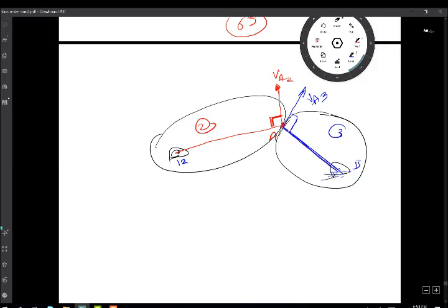And so on each link it's not the same velocity, because the way the contact is made is all based on geometry more than anything. And in this case, that's not rolling contact, right? So you can say sliding contact. It's really a combination of rolling and sliding, and that's more of what a higher pair can be: a combination of rolling and sliding.